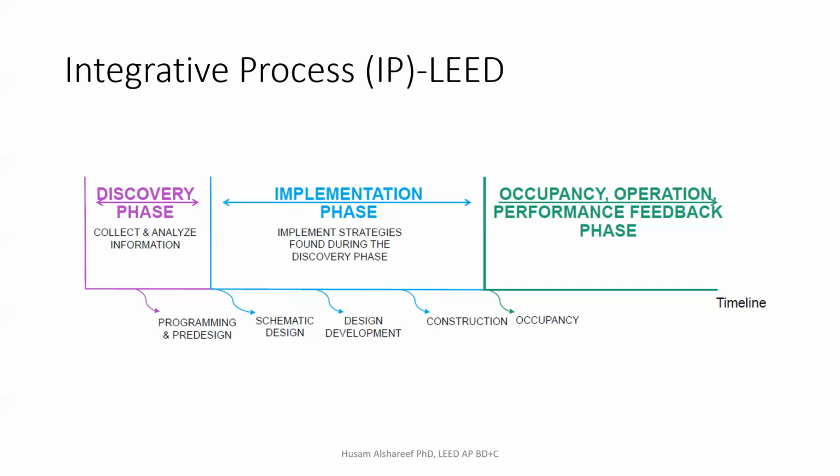And then once the schematic design finishes, we move on to the design development, which pretty much develops the building or project in detail, down to the level of colors, materials and quality. And then once this phase finishes, we develop the construction documents, which is another phase of the design phase, to prepare the project for bidding.